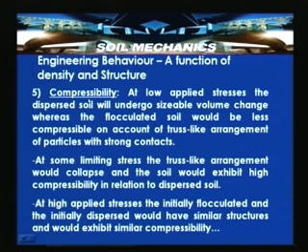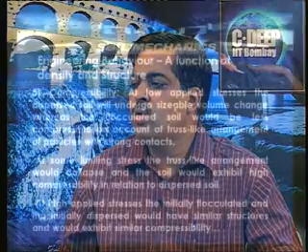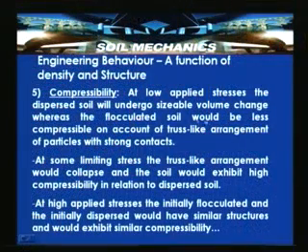Now, coming to the compressibility. Compressibility at low applied stresses: the dispersed soil will undergo sizable volume change, whereas the flocculated soil would be less compressible on account of the truss-like arrangement of the particles with strong contacts. So, if you compare, at low applied stresses, the dispersed soil will undergo sizable volume change, whereas the flocculated soil will be less compressible on account of the truss-like arrangement of particles with strong contacts.